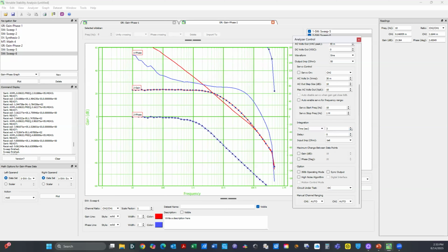The longer the integration time, which is sort of the inverse of what they call a bandwidth on a network analyzer. Usually the network analyzers use bandwidth frequency to set how long they're going to accumulate data, whereas we use time. Since we're making very noisy measurements, we use long integration times because that gives you very narrow bandwidth.